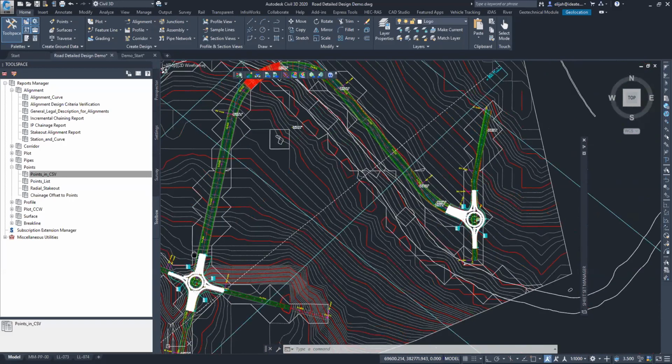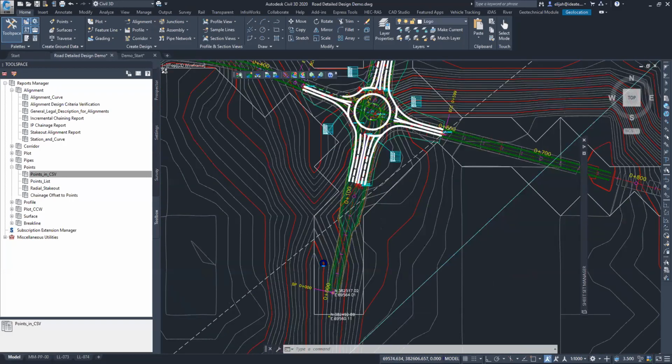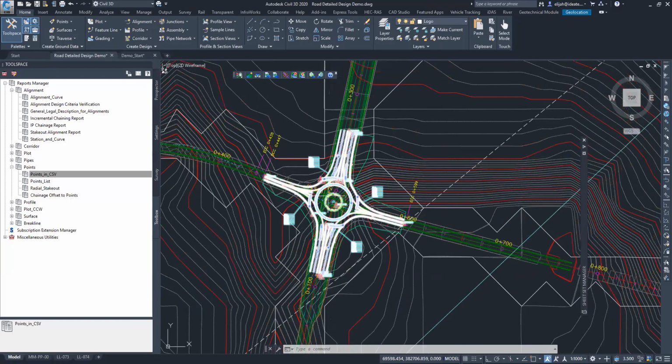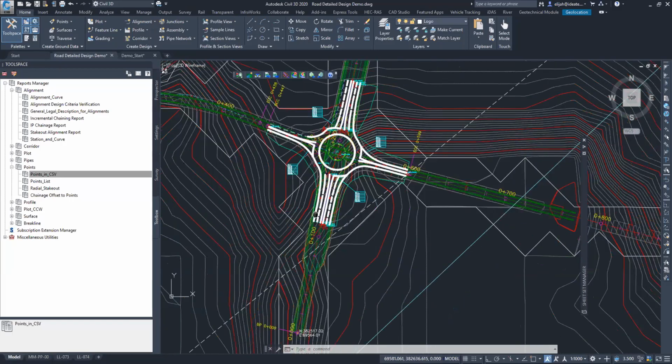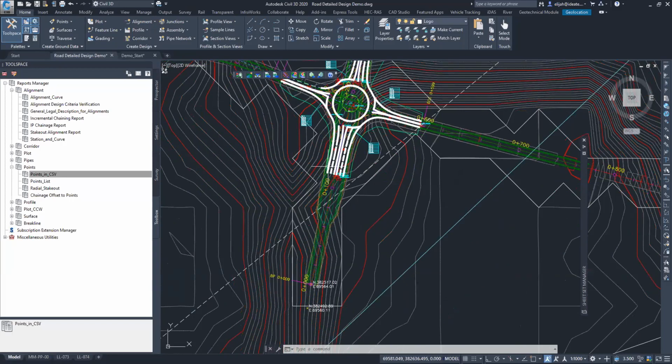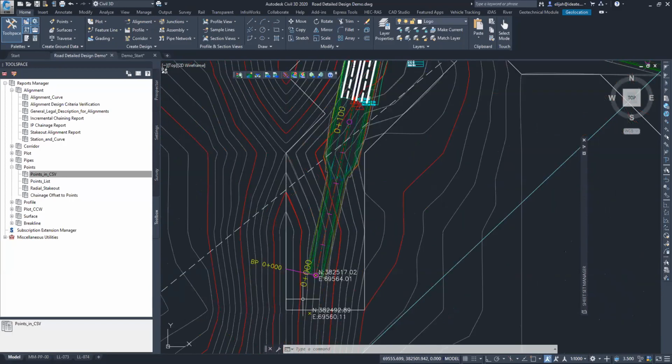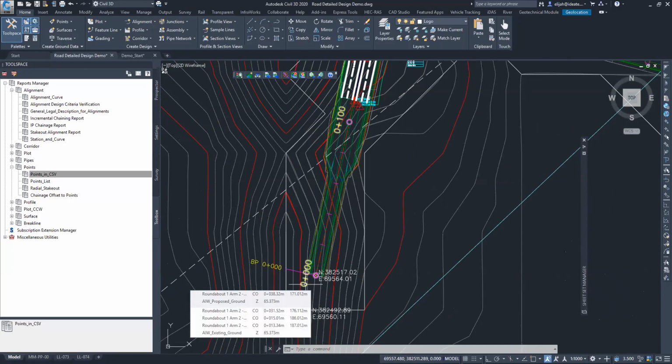Since they are just randomly created for specific points along the road, we can specify to the software that instead of giving us only some specific points, generate for us points at an interval. So whether it is a 20-meter interval, 10-meter interval, 15, or basically determined by what you call a sample line, the way the road should be sampled as you start from the beginning going through up to the end.